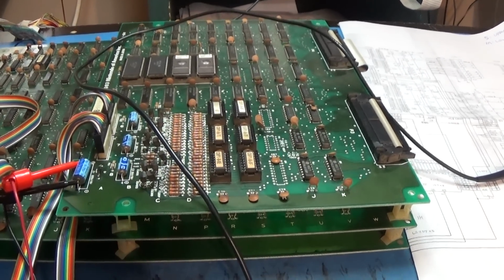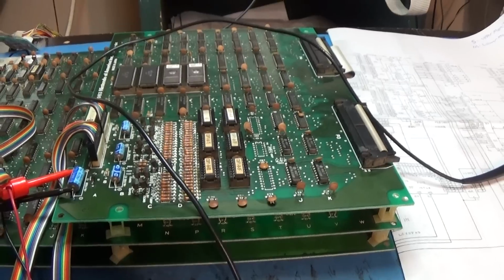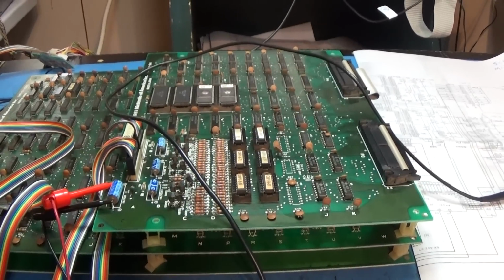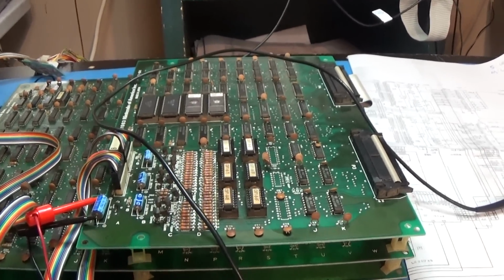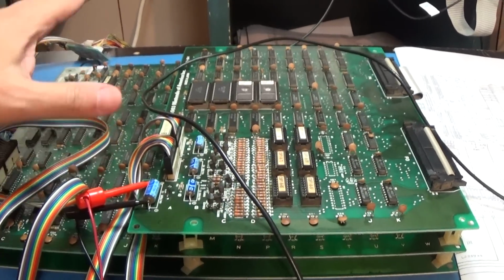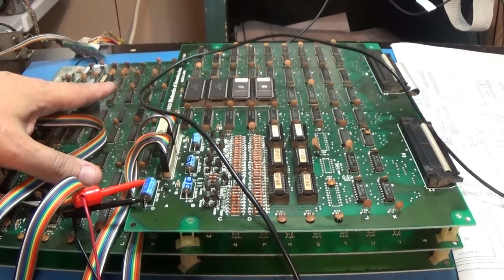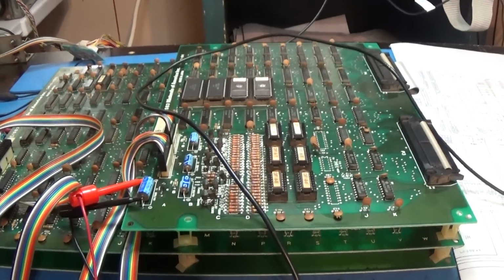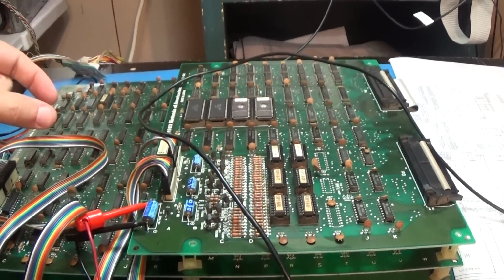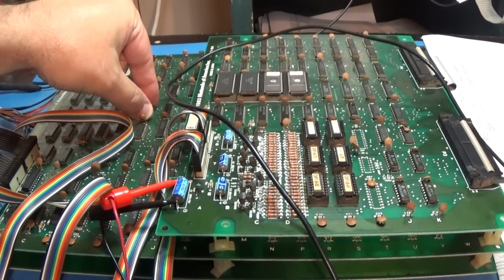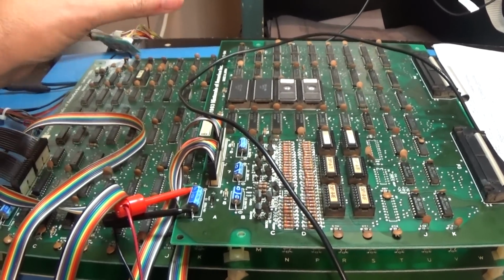Alright, I was doing a little thinking, and I recently did a Punch-Out PCB repair. If you remember, it had a bad counter in the DMA circuit on the CPU board. If you went back and looked at that video, I jumped a good 161 over the bad chip, and the board came back to life.